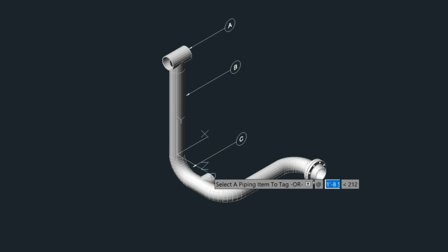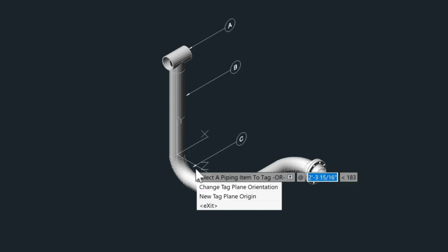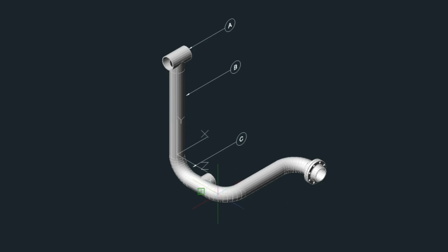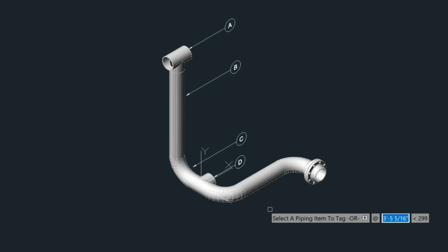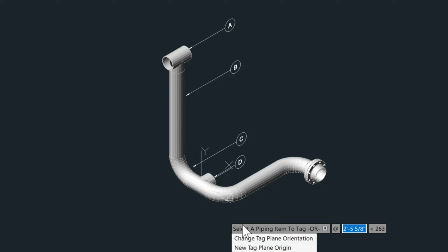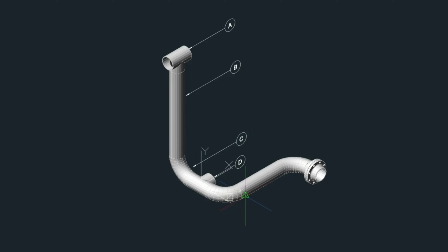And now that we're rounding this bend here, we need to reselect the origin. So we arrow down and select the origin here at the center. We'll come out, start the T, and enter. Now we're going to be, again, rounding that corner. So we'll select the new plane origin here.